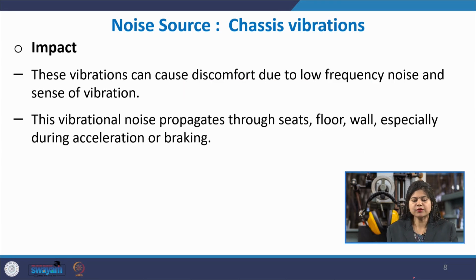What is the impact of this? First of all, this noise is propagating through the chassis or the frame in the form of vibrations, and whenever the vibrations exceed the coincidence frequency, they radiate into the air. So here the impact is twofold. Obviously, the vibrations will cause discomfort due to the low frequency content in them